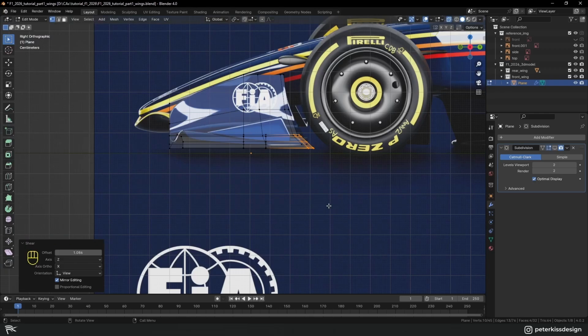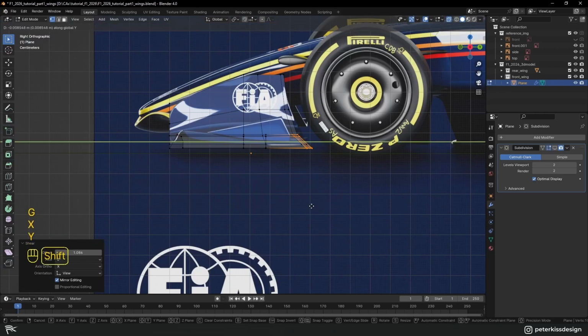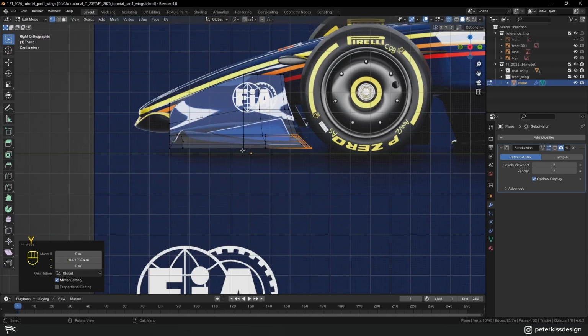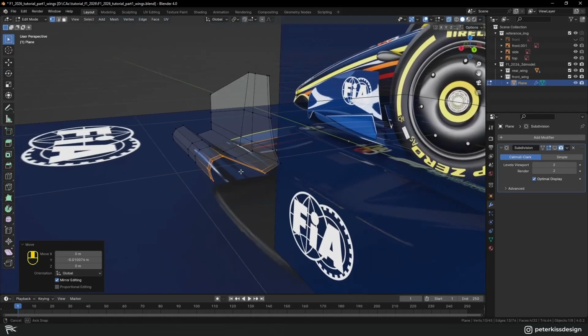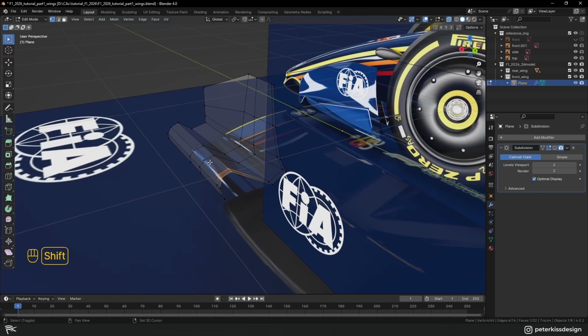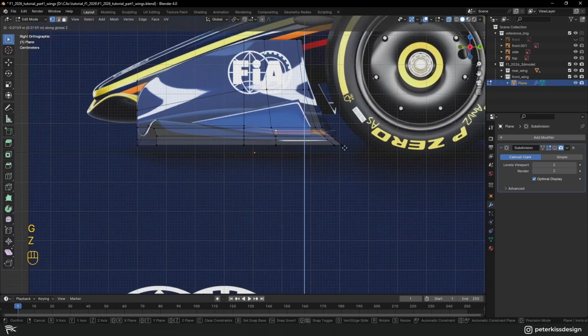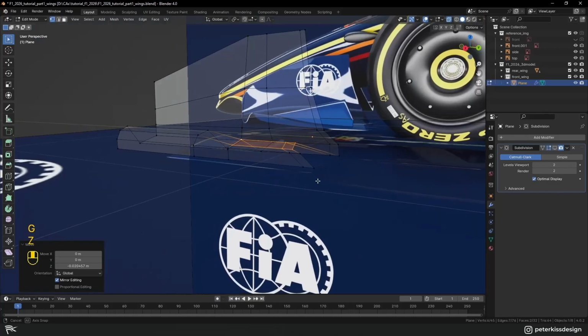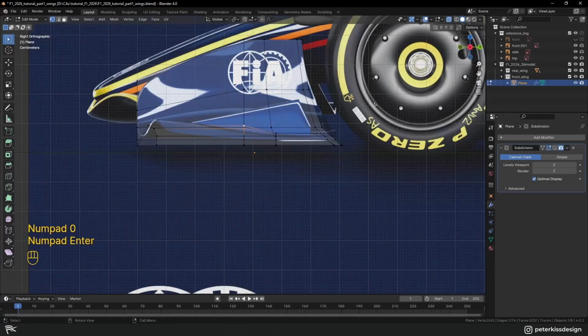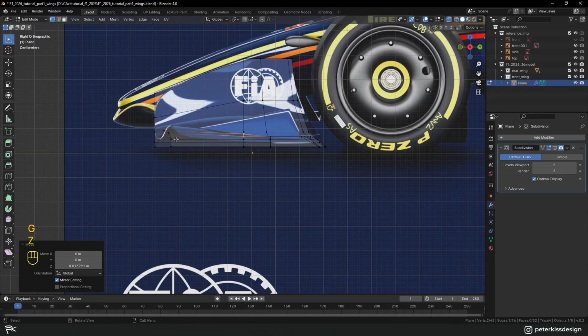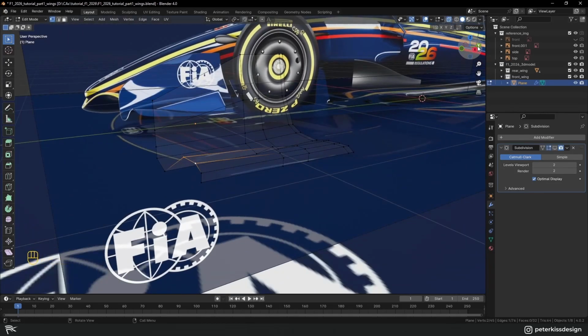In the side view we can see that it gradually changed its shape towards the front, so now we will select the top vertices and move them to the correct position according to side view. Select these 6 rear, move them down and scale them to 0 in Z-axis. Then select the middle one, move them a little bit down, select the front and move them up.